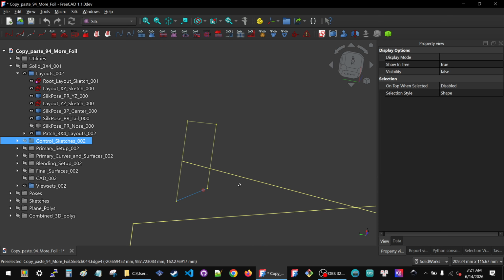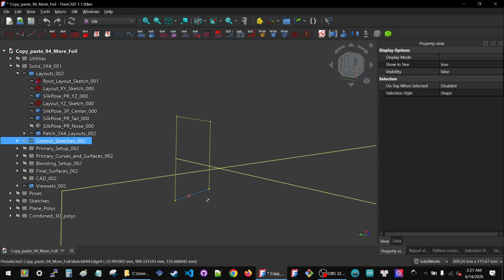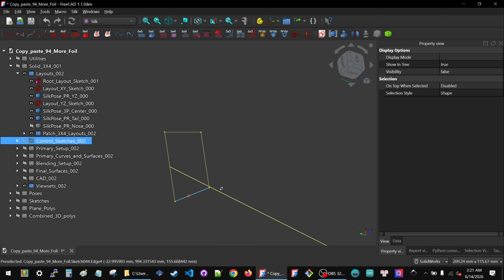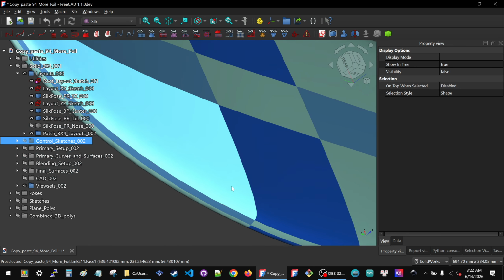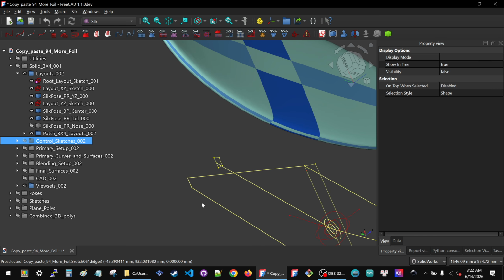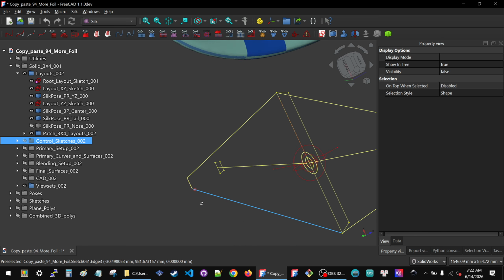So these two lines are parallel. That means we only need to create one plane that has the correct orientation, and then we'll be able to clone it over to the other side. So of these four corners, one of them is going to have a relatively easy way to create the orientation we want. And it's actually a little bit of a trick when you know you're not going to get the orientation you want: work in reverse right off the bat.